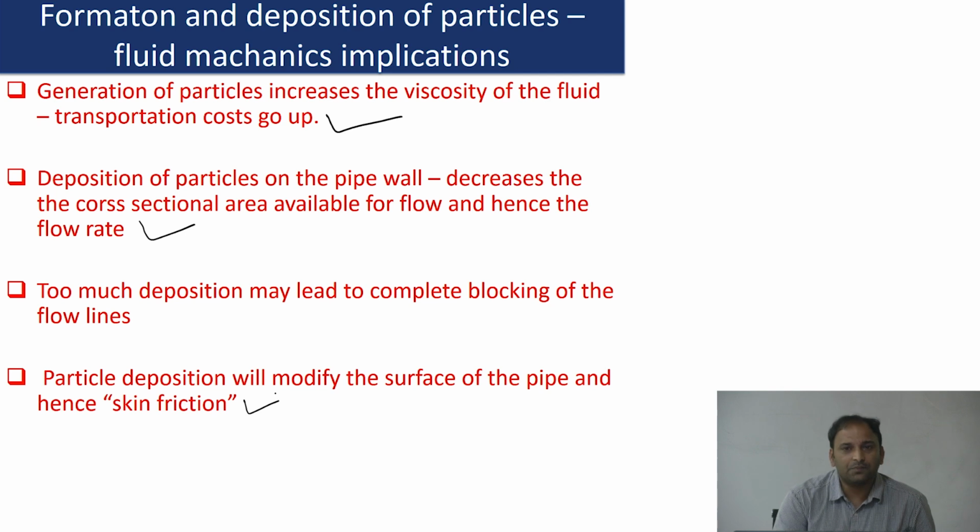And in the previous lecture, we talked about skin friction and form friction, right? And we said that skin friction basically comes from the roughness on the inner wall of the pipe through which the fluid is being transported, right? Now, when you have wax deposited, obviously it's going to affect the surface properties, right? And therefore, it is also going to affect the skin friction. So the formation of particles is of relevance both in terms of trying to understand when the particles form, as well as to look at fluid mechanics aspects. Yeah, somebody has a question.